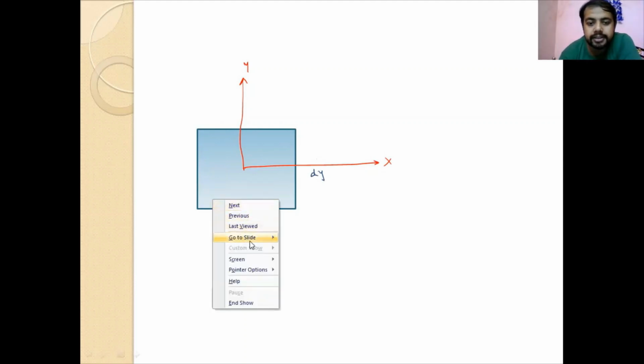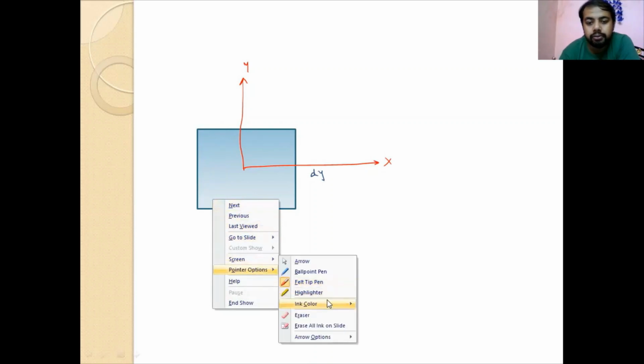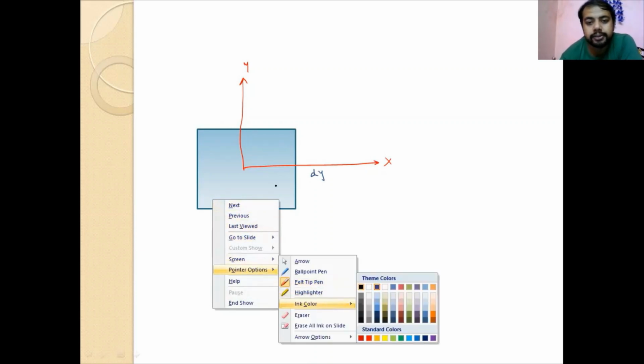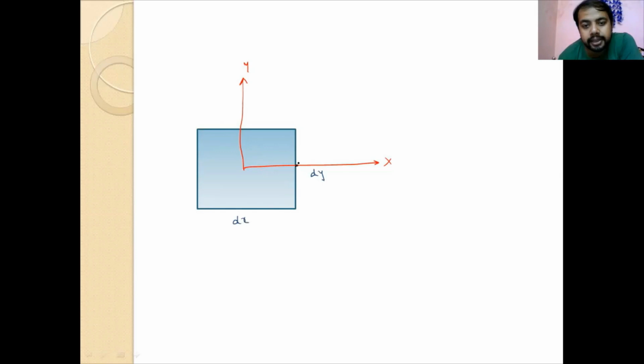Now, what are the stresses acting over it? Over the surface here, normal stress is acting. You write it down: tau 1 1. Is it understandable? If you draw a normal over this area, it is along the x-axis and the force is also along the x-axis.